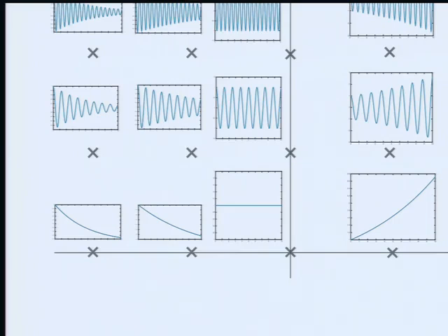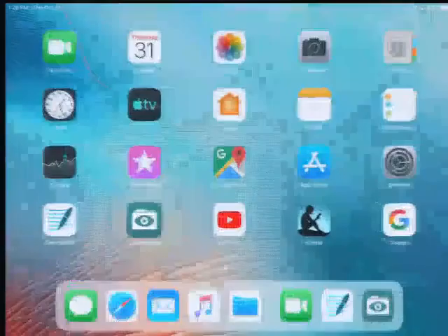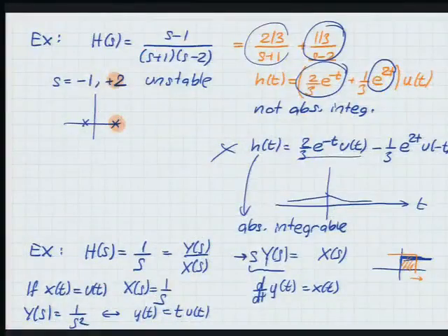If you have a pole with an imaginary part, that means you have oscillations. If you apply an input that has the same oscillatory frequency, then the convolution of the two will grow unbounded. Okay? So one is enough. I can apply a sinusoidal thing to an integrator, it doesn't blow up, but that doesn't mean it's stable. There's another input, which is a constant, that will drive it unbounded. All right, so I think this will make for good homework problems. I'm thinking as I'm teaching. All right, one example to finish this discussion with.